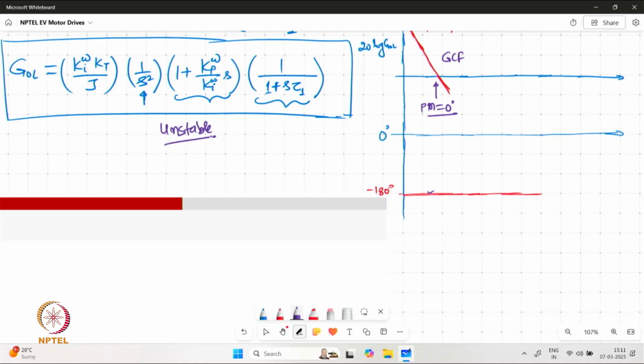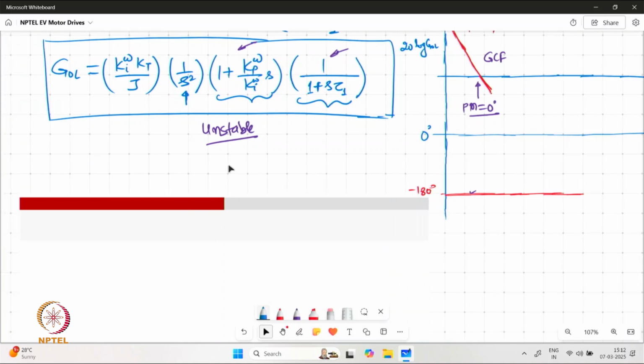and therefore we need to take some corrective action for the phase margin so that the system can be made stable. Now this is not possible through the pole zero cancellation of this part, because these are frequencies which are located much farther from the gain crossover frequency, until and unless we make some corrective action over there. So which is why we go for a method for solving this scenario, and that is called the symmetric optimum method.